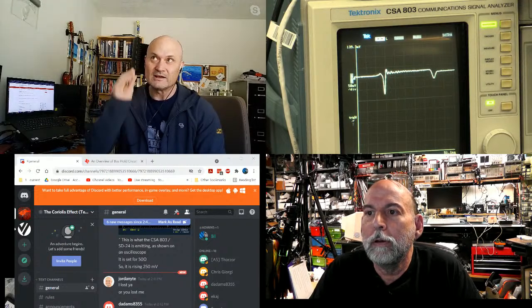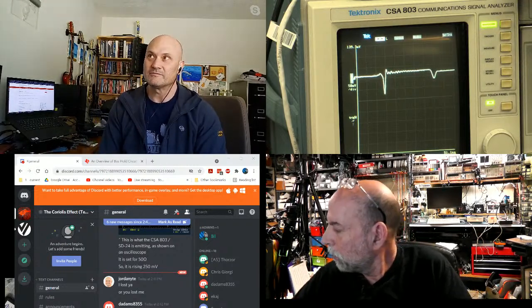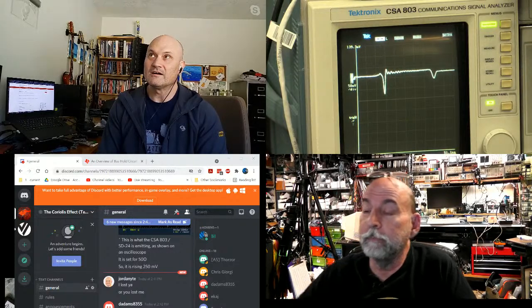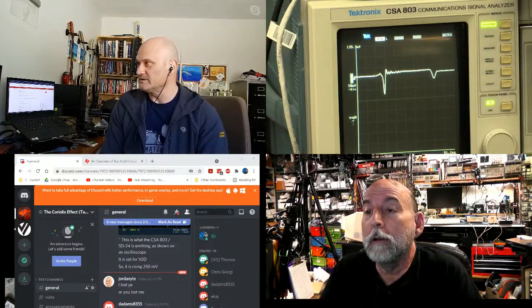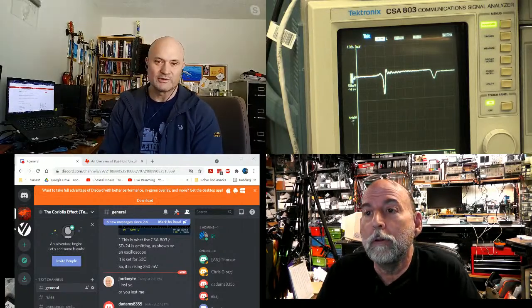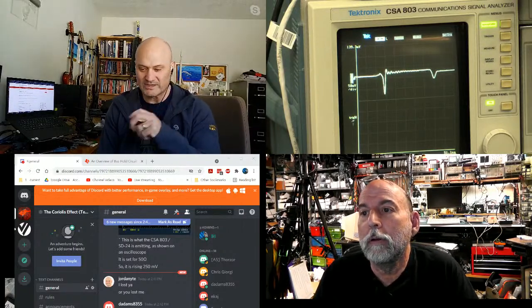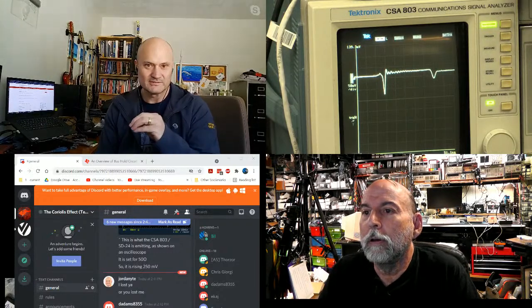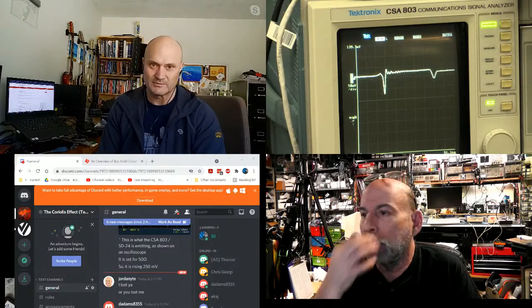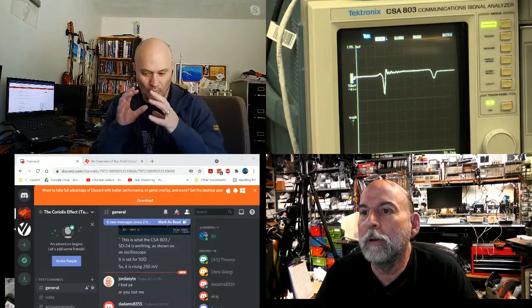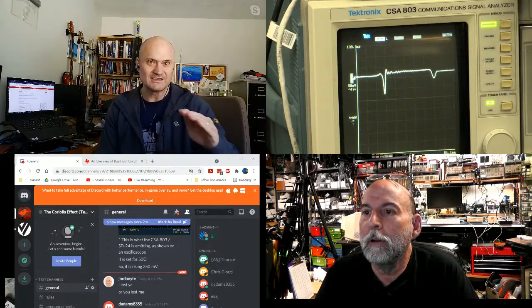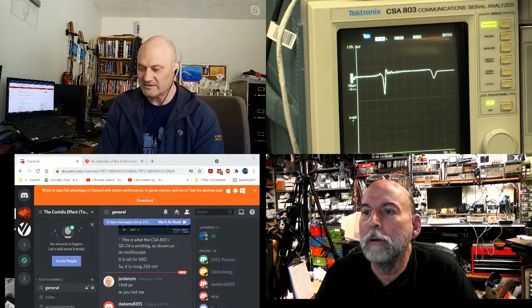We could talk about cooling someday. I could probably run a board through it, but the point is, you can put heat generating loads assigned to different parts on the board, and say, like, this MOSFET here is dissipating 1 watt. What does that contribute to the overall heat? And do we exceed temperature for our design?